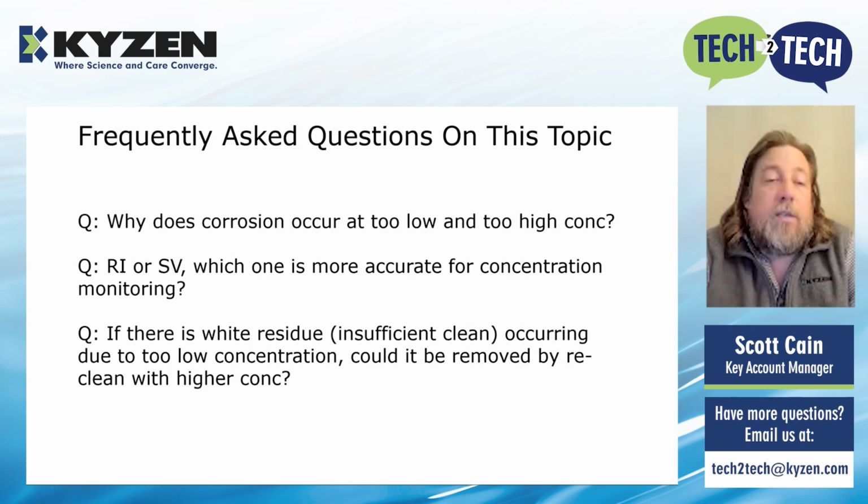Between the refractive index and sonic velocity, which one is more accurate for concentration monitoring? The sonic velocity is a little bit better because it takes any of the manual variances out of it. If both yourself and myself were to do the refractive index, how we're pulling that sample, what the temperature is, and how long we're waiting before we compare it to the brix is going to vary just a little bit. Whereas with sonic velocity, it's consistent because a machine is doing it. It is doing it the exact same way every single time, reading that information.